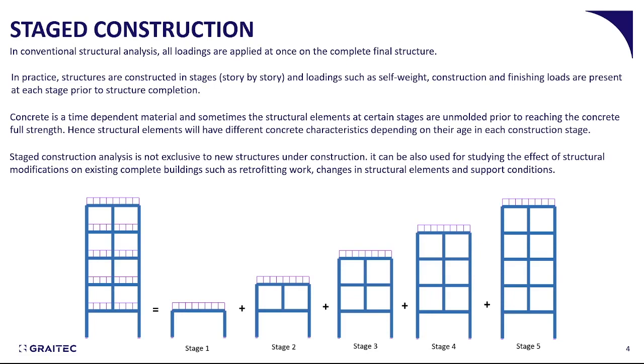This is basically the reason why staged construction is important and why construction phases should be considered, especially when modeling structures that are primarily made of concrete, because the time-dependent properties of concrete might affect the results either positively or negatively, as we will see later on when we do the demonstration in Advanced Design.